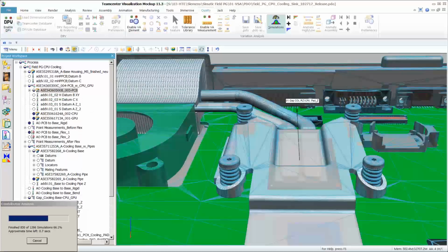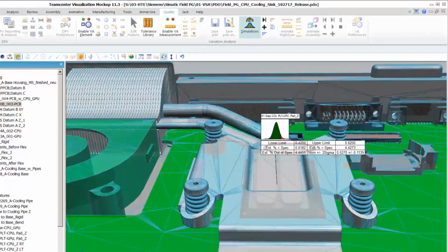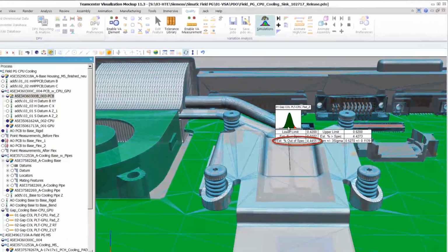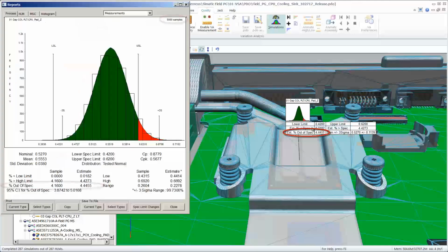Now you see the results of building 5,000 laptops. It shows 4.45% out of spec. This is about 95.55% good quality rate, below the required 99.73%. Most of the bad products seem to have larger gaps, which could cause excessive CPU heat and fan noise. Increasing the preset torque of the digital screwdriver may shift the gap down.